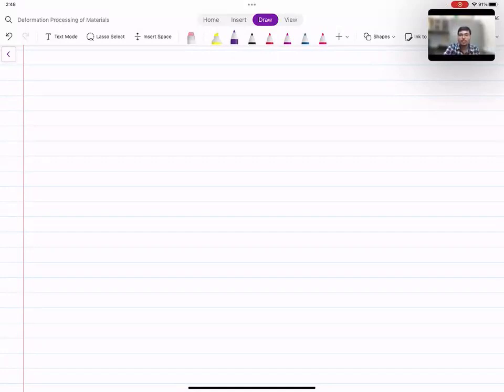So what happens is that these oxides now get passed into the extruded product. They are present in the form of defects in the extruded part, and if we cut the cross section and see this section of the extruded portion, it appears like an annular ring.